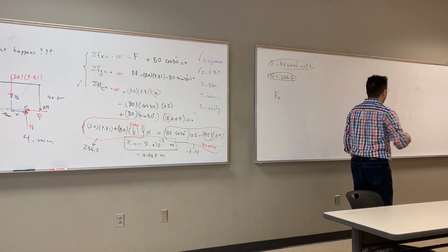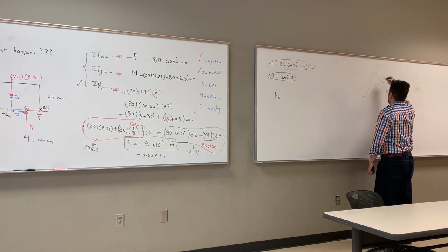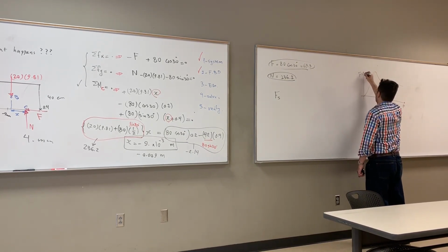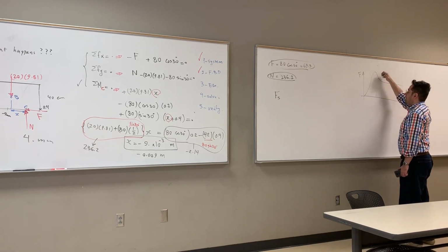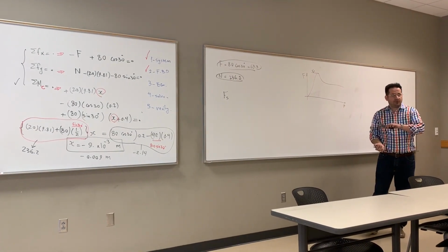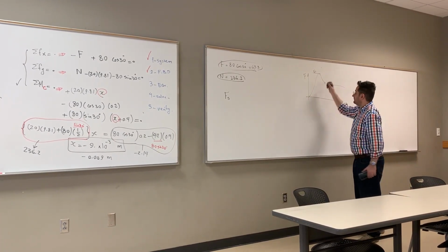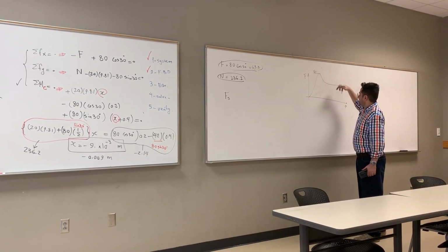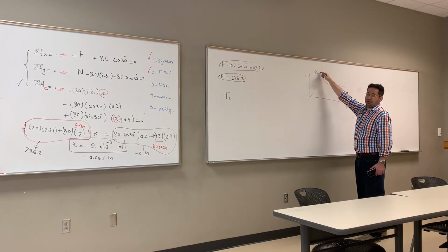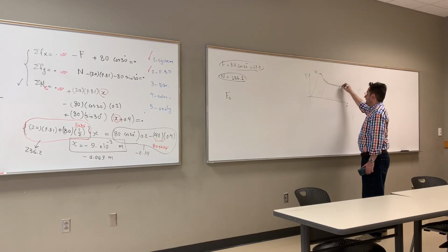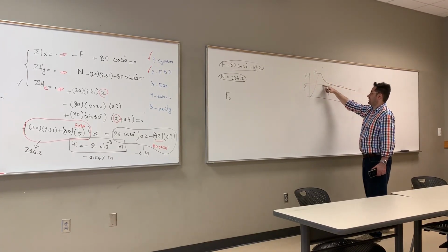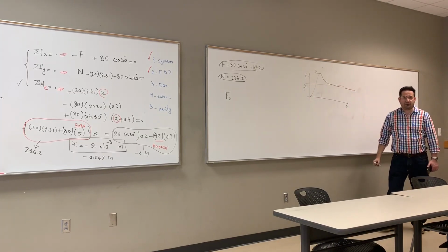You remember last time we had a graph of this, and say if you increase P, the friction force is going to go up, and this is Fs, the maximum equilibrium friction force. After that, if you increase P, this F is not going to go up. It's going to go down. And then this is the terminal value, the kinetic, K. It's sliding with constant velocity, right?